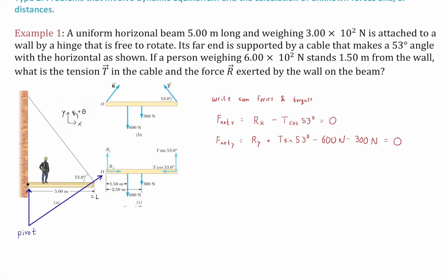because we have positive Y pointing up, positive X to the right, and, very important, positive theta, right? So positive angular movement in the counterclockwise direction. These would all be the typical choices. So now finally, our sum of torque equation. And this is relative to the pivot. It has to be, okay? Not that we could choose, we could have chosen a different pivot, but this was a good choice, all right?